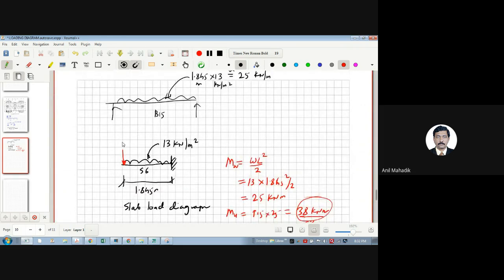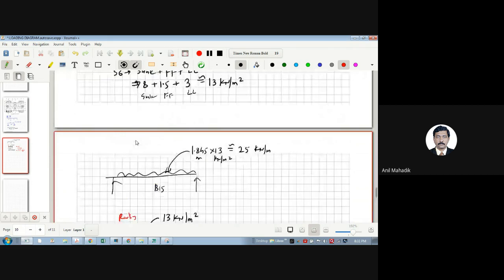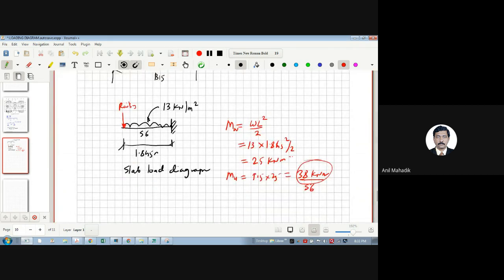So ये वाला glass railing load समझो. So you can calculate the railing load by assuming some thickness and steel का weight वगैरह निकाल के. And then you can add in this moment. ये point load समझो, let's say 1 kilonewton is the load of the railing. Then 1 kilonewton into 1.845. So it will be additional moment. Roughly it will be say 27 total. And then you need to design for 27 for S6. So this can be the choice of designing such kind of slabs.